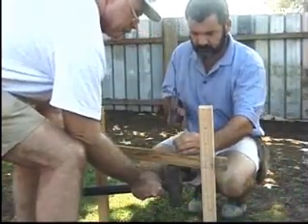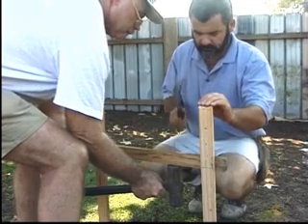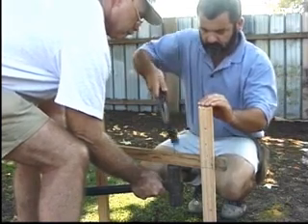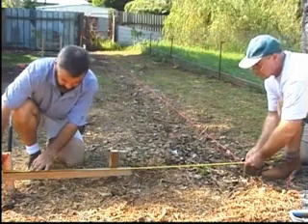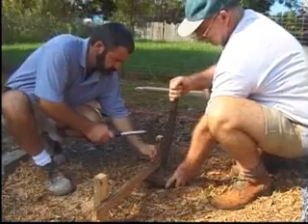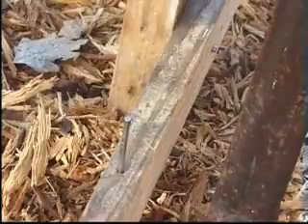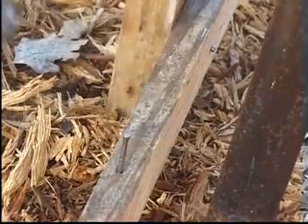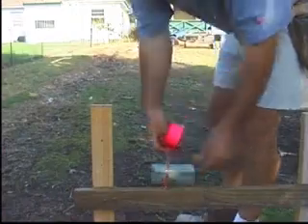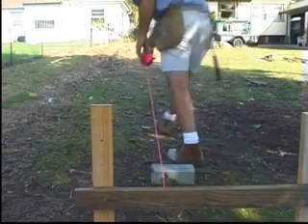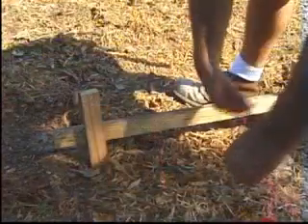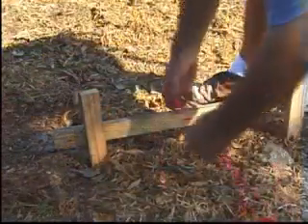These measurements are marked on the tops of the ledges and nails located on the marks. A string line is fastened between the two nails and tensioned.